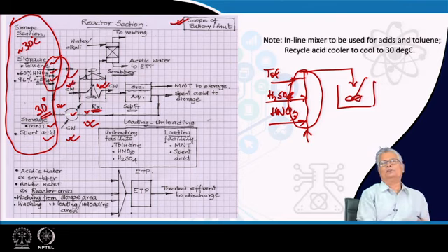Possibly some sort of tubes, or it could be even jacket. Possibly in this case, since the rate of heat generation is high, just providing an external jacket may not suffice, and what we have found while we have checked this is that you require not only a single row of tubes, you require several rows of tubes here to remove the heat. We will see the details later on.